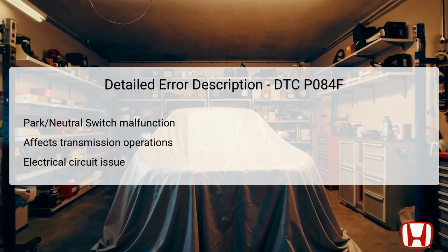This can lead to incorrect vehicle behavior, such as being unable to shift or start the engine. Electrical issues may arise from loose connections or damaged wires, making this DTC crucial to diagnose promptly. Understanding the layout and function of the park neutral switch enhances troubleshooting accuracy and efficiency.